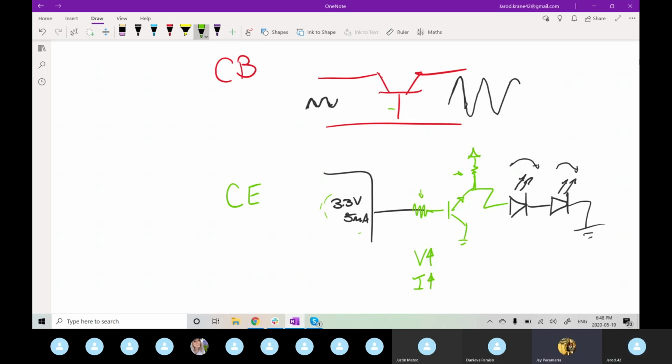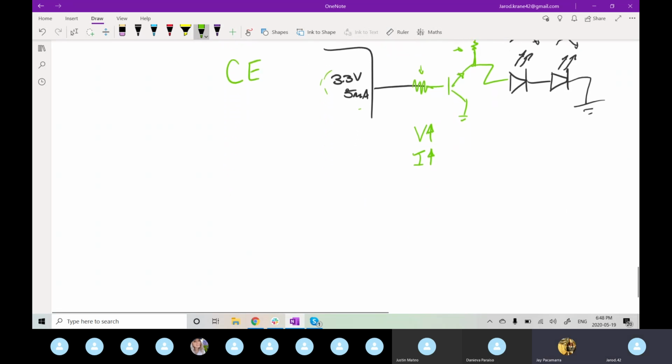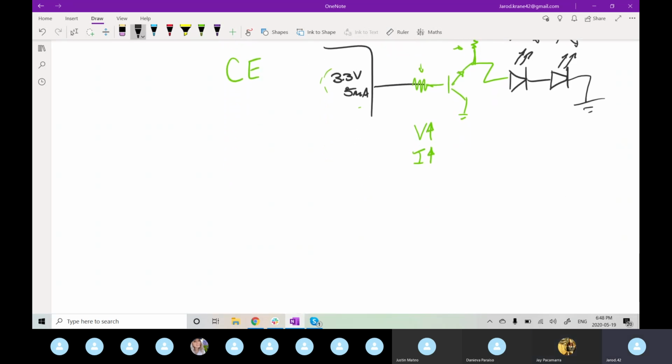When do you use an NPN transistor and a PNP transistor? Yeah, good question. So, kind of the final point I have on NPNs is their typical use case is as a low side switch, whereas PNP will be a high side.